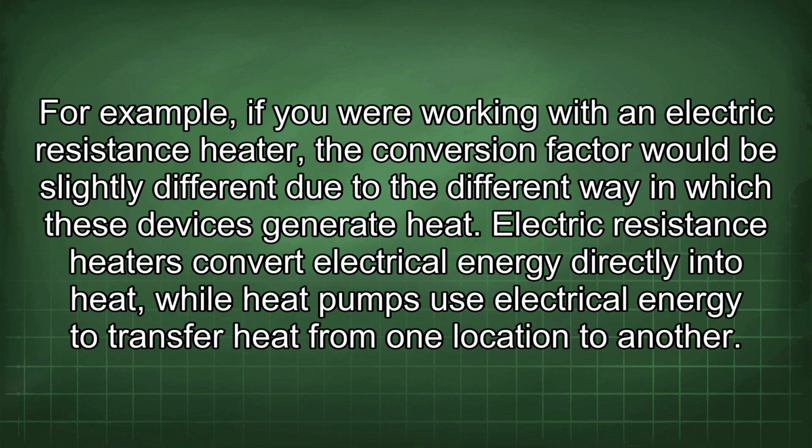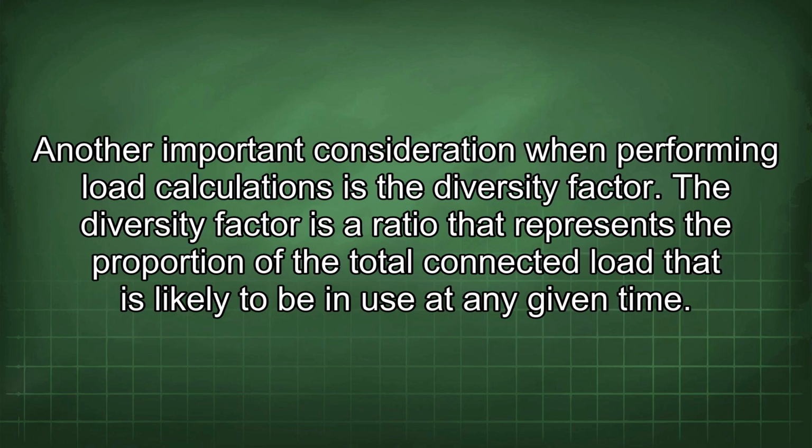For example, if you were working with an electric resistance heater, the conversion factor would be slightly different due to the different way in which these devices generate heat. Electric resistance heaters convert electrical energy directly into heat, while heat pumps use electrical energy to transfer heat from one location to another. Another important consideration when performing load calculations is the diversity factor.